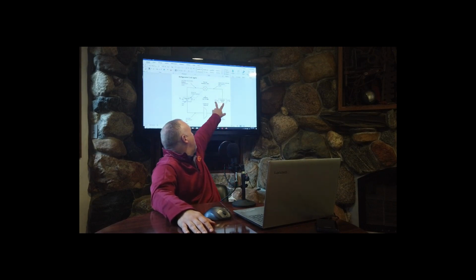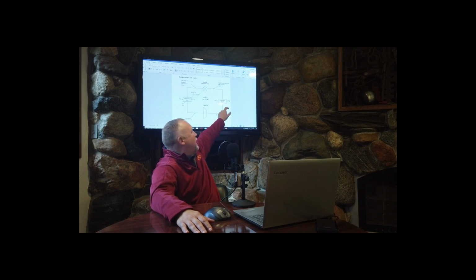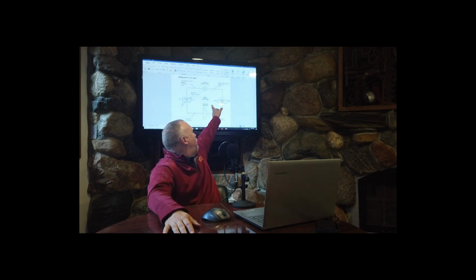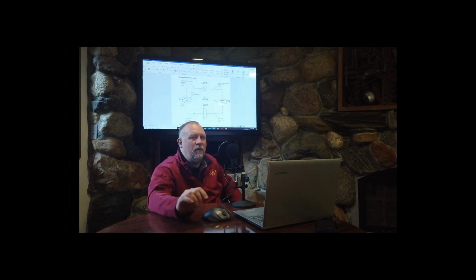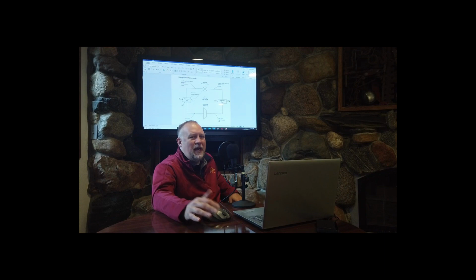One important thing to note: see these temperatures? Like I said, I'm on page 21. But these temperatures are for ambient air. The ground is much cooler, even in summer, obviously much cooler than the ambient air. So the water that we pump down into the ground can also be much cooler. If that average ground temperature is, say, 60 degrees in the summer, the condenser water temperature only has to be about 70 degrees to reject heat to that ground.